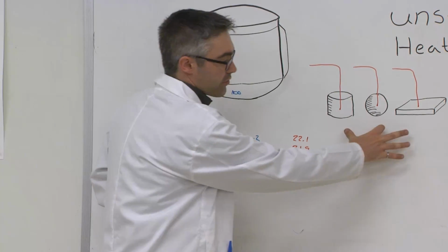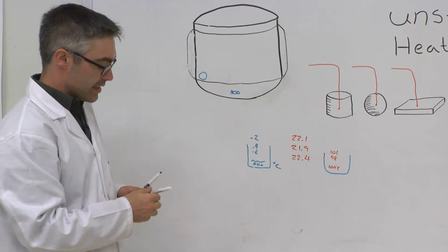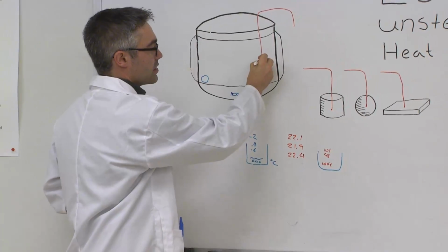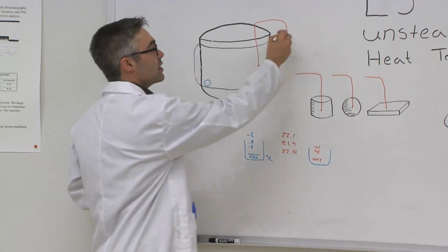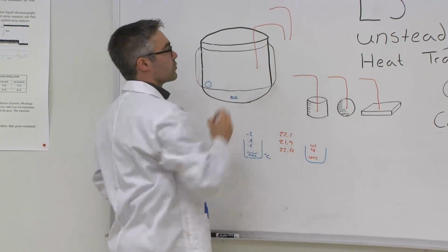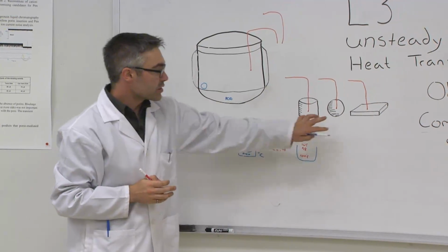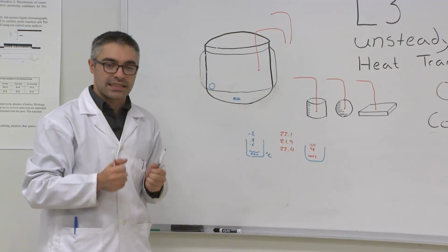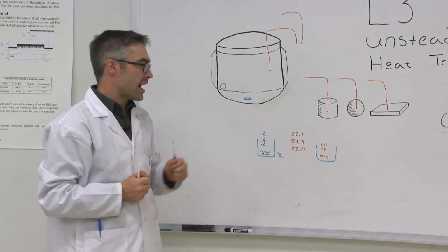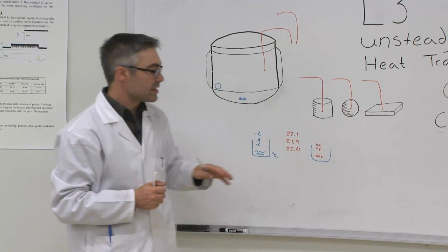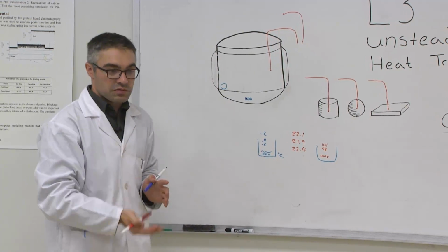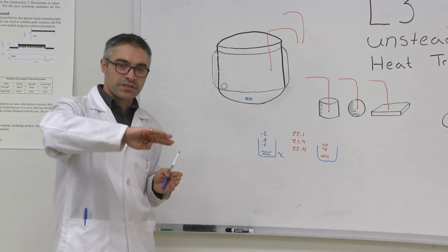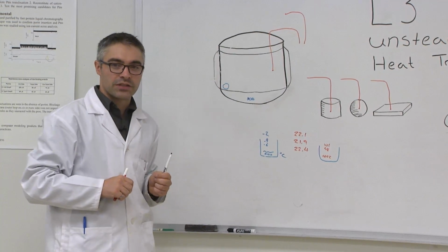Once our entire bank of thermocouples has been calibrated, including one to simply put into the water to measure the environmental temperature, and one to put at room temperature to measure the room temperature, we will then immerse each one of these into the bath and begin collecting our data continuously. It's imperative that you have all of the temperature measurements monitored as quickly as possible so that you can see the temperature changes over time and ascertain the shape of the curve.